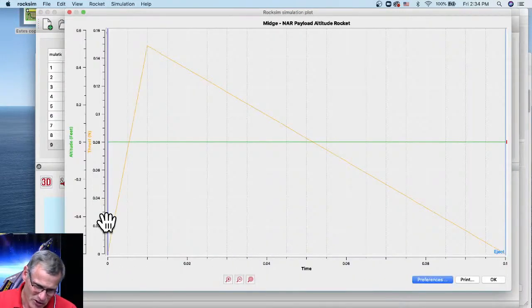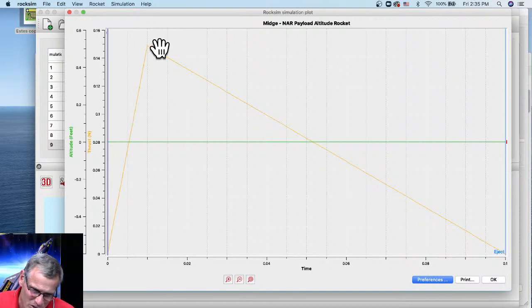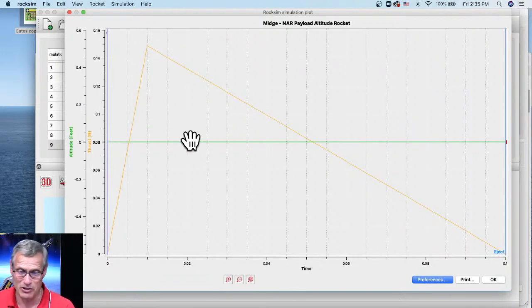So here, see the yellow line right here is my thrust curve, and it should match that thrust curve that we created in Engine Edit, and has a burn time of 0.1 seconds and reaches a peak thrust of 0.015-ish newtons. And the rocket just didn't have any amount of thrust to get it off the pad. So our fake motor is working. So that was what I wanted to just demonstrate.